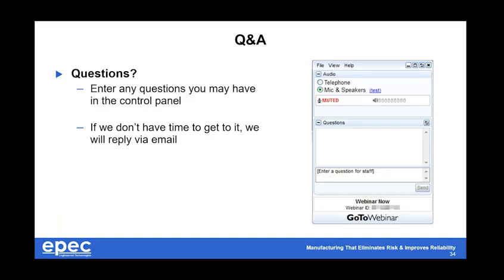What's the most inexpensive UL rated wire you can offer? I did mention this at the beginning. That would be our standard PVC UL wire. Typically, those are the single conductors to the tune of UL 1007 or 1569. So typically, anything that's going to be PVC based is our best and lowest cost option for you to consider.